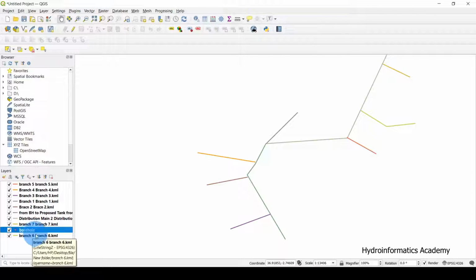Okay, so this is our shapefile, and what we need to do is to make sure that we create a point here by using this shapefile. So I'll just click this shapefile, then I'll just go up here. You can see that we have this toggle edit. I'll just click this toggle edit. Then we are going to click this add point feature. Okay, so from here, add point feature is active.